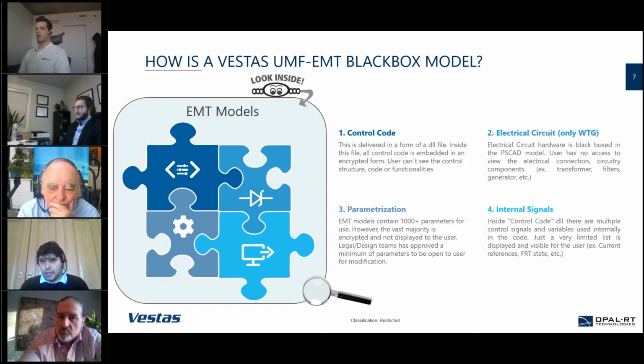But another thing is that you need to make sure your electrical circuit, your hardware in this case, is accurately represented as well. So that means that you have to represent your inverters, your IGBTs, your filters, and everything accurately in the model to make sure the final performance of the model resembles the real product. And then we go to the third leg of this, that is the parameterization.